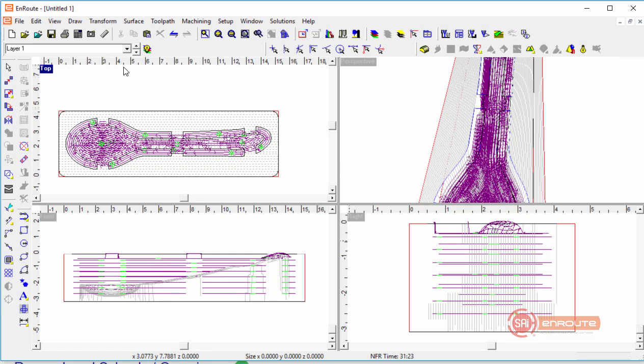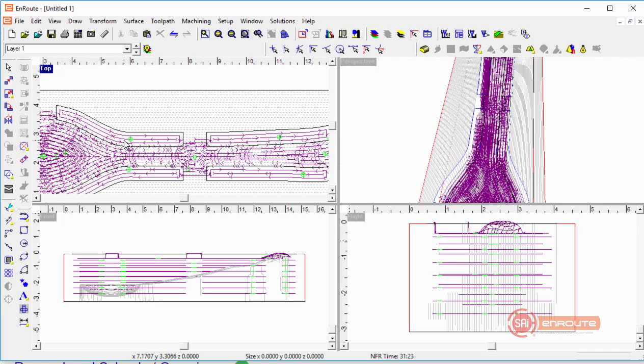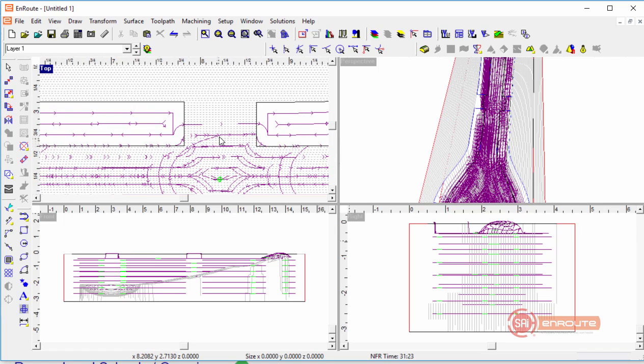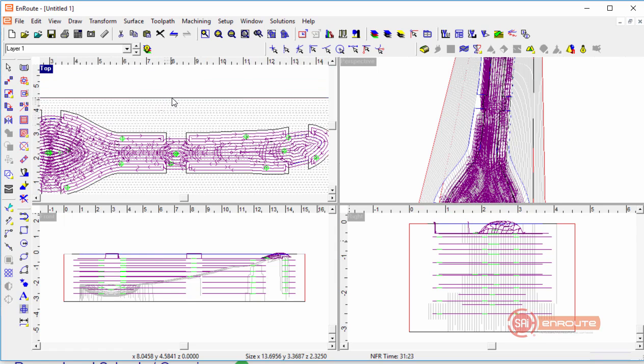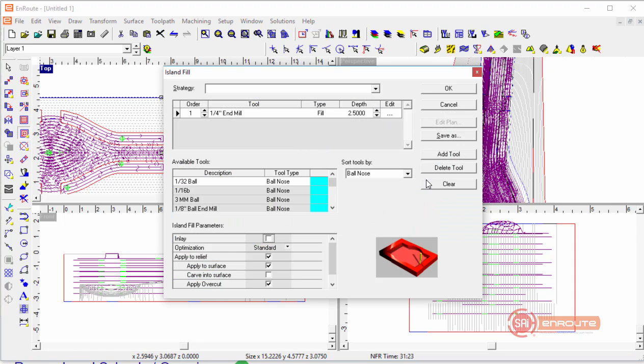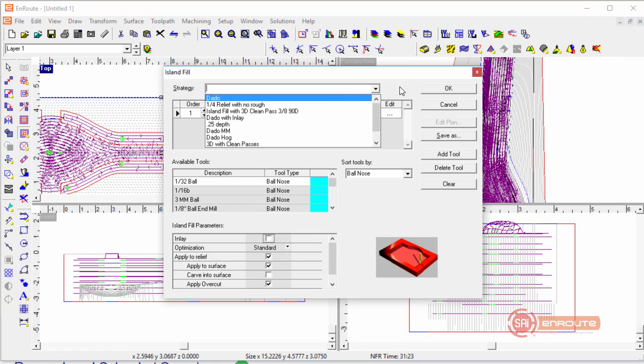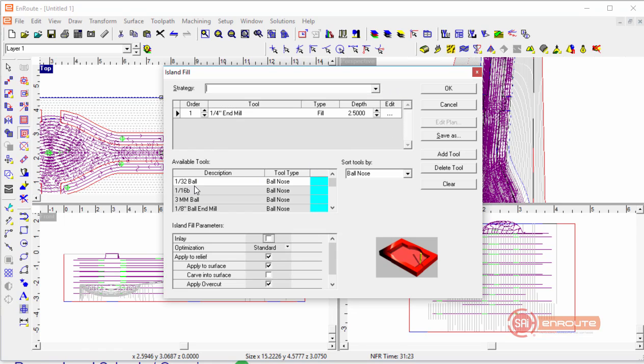All right, now the final toolpath we want to do, we want to get back there again and select this particular shape, and then the relief. So that's the masking toolpath and the relief itself. We need to do one more toolpath here. We need to use our ball nose tool. And this time we're going to go down 2.8 inches. This is going to be the detailed cut.